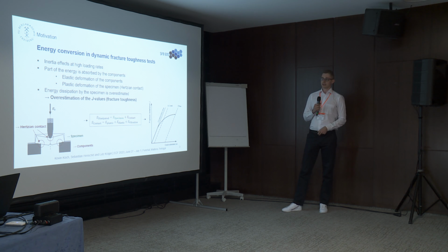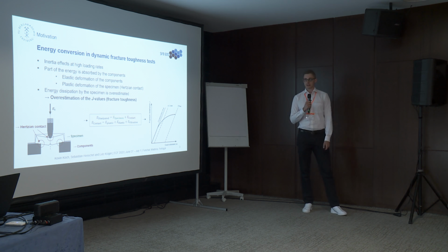The energy which is absorbed and dissipated can be estimated by the load line displacement, for example, measured at the tup. However, part of the impact energy is also absorbed by components, such as the support or the tup.